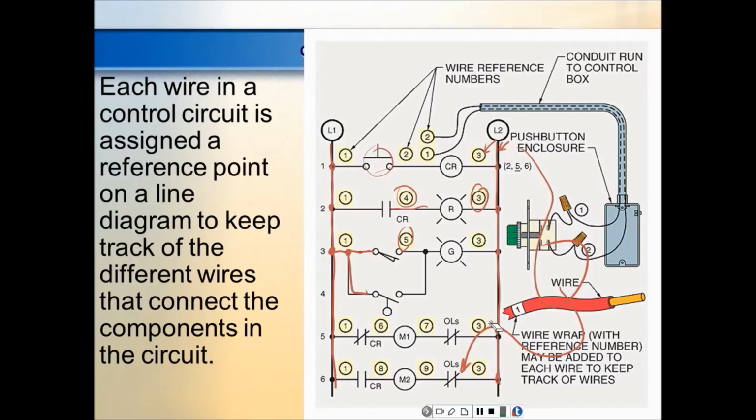On the airplanes, all the wires on the airplane I worked on were white. And they literally burned the wire numbers into the jackets, and they put them every 6 inches. But everything you look in there, you'd have a bundle of wire. If they took all the wires in the airplane I worked on and spread it out, it'd probably go around the earth. It was a lot of wire. You'd see wires that big, and they didn't use cable, they used individual wires. And then they were tied together. But they don't use the plastic wire ties, they use the wax string. It was beautiful. Learning how to run that wax string.